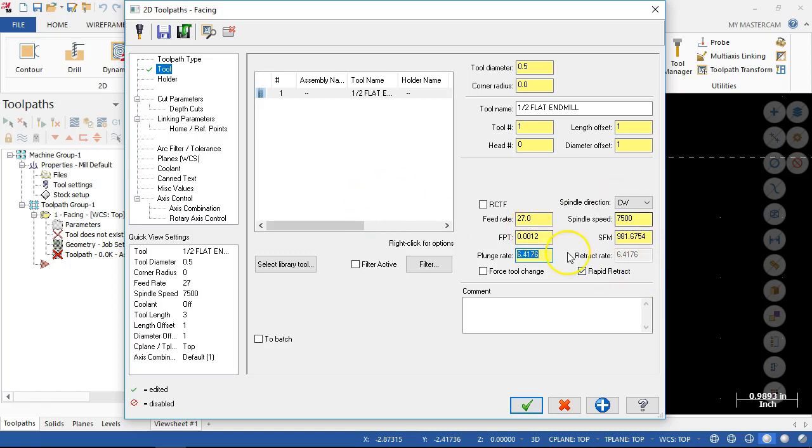All right, so all of this is just a juggling act. You're picking numbers based on the control, the rigidity of the machine, the material that you're using. It becomes certainly a lot more critical when you're into the stainless steels, the tool steels, the high tensile alloys and super alloys, where an inch a minute may be too much because you have to run it at low RPM, get it fully engaged.